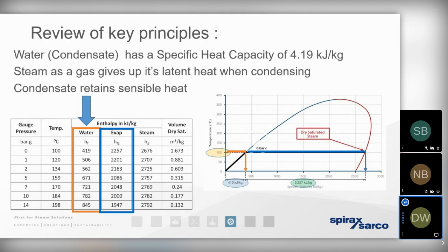We're more at risk of any dry steam that's passing across that trapped puddle of condensate degrading. So there's going to be less energy contained within the steam as well. But it also means that if we are using that steam for direct injection purposes, that steam is more likely to pick up droplets of condensate that's going to be entrained within the steam, together with any iron oxide, rust, or scale that exists as a result of that foam being carried out of the boiler. All of that runs the risk of being injected directly into any process that we may be using direct steam injection for. So keeping the steam as dry as we possibly can is valuable for a number of different reasons.